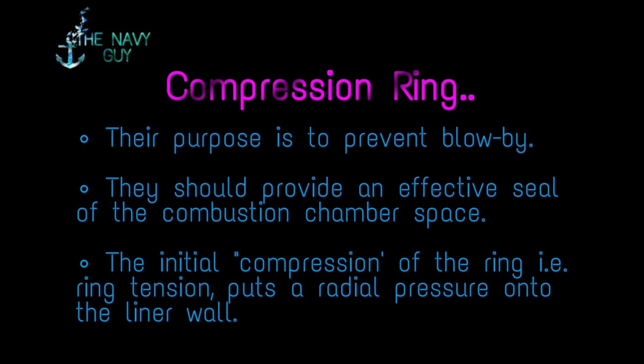There are two types of piston rings attached to a piston. The first set is of compression rings. Their purpose is to prevent blow-by. They should provide an effective seal of the combustion chamber space.